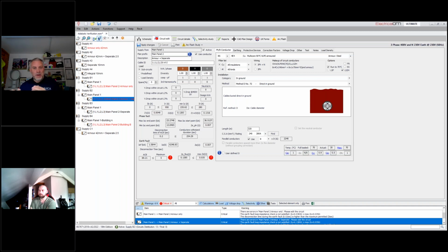This is about a 750N duct, so a twin wall duct offers enough mechanical protection in line with regulation 419.3 that you don't have to use the armouring as mechanical protection for that cable. As long as the cable's bonded at one end, you don't have that SWA effect. You can ignore the armouring as the CPC.